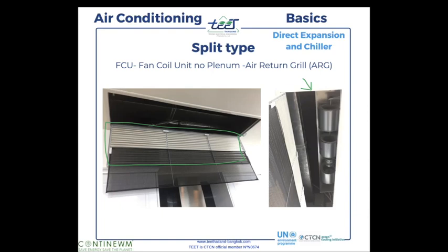And sometimes when they do this, you can have the feeling that they don't always do things in the right way. And you must have, in general, around this hole and around this grill, some kind of plasterboard wall to guide and suck the air only from this grill to bring to the FCU, because otherwise you have a big area, okay, with a lot of air coming from multiple places, so it's not super efficient, but it works.